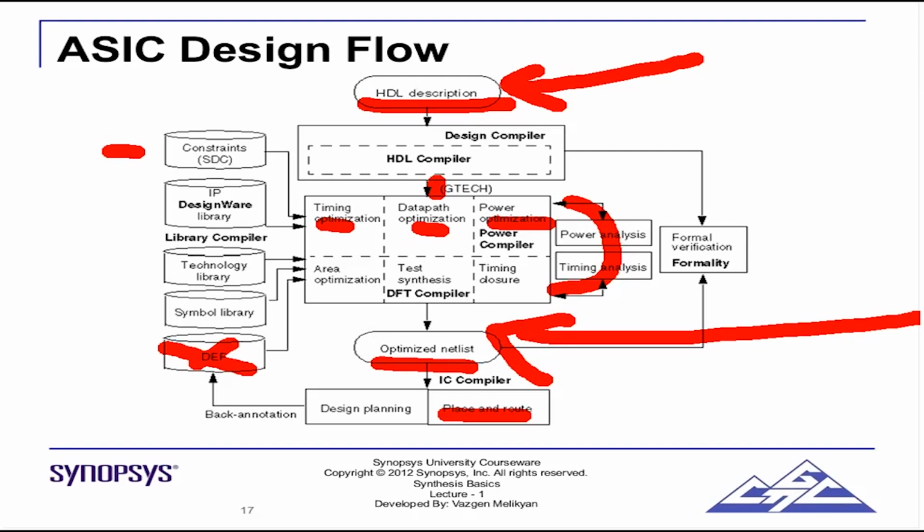Please note, this does not mean that the Synopsys Design Compiler tool here has some problem. It can mean that whatever HDL description we wrote is not actually good enough to produce a good netlist. There can be many reasons why these two are not equal. But we will see in the process of synthesis what those reasons could be. But we have to make sure that these two are equivalent. The process is called formal verification. Formality, we'll look a bit into this during this course.